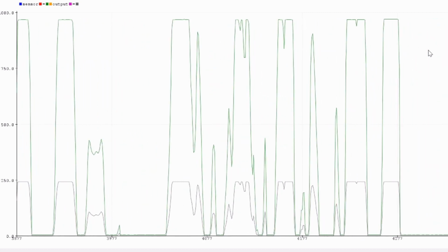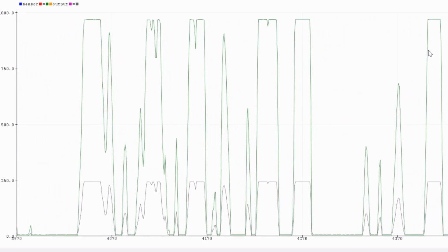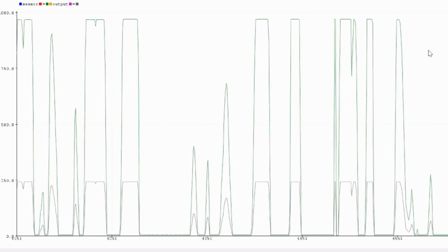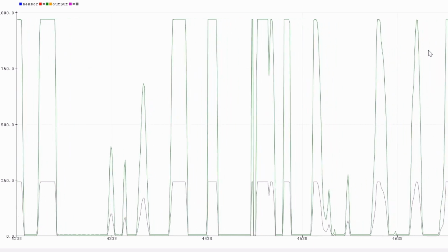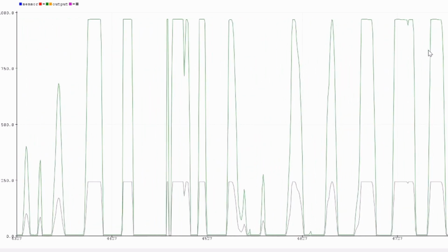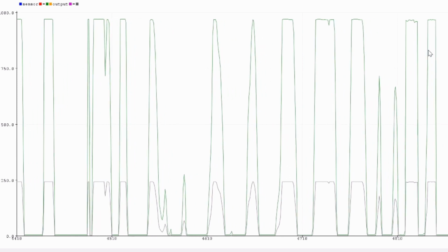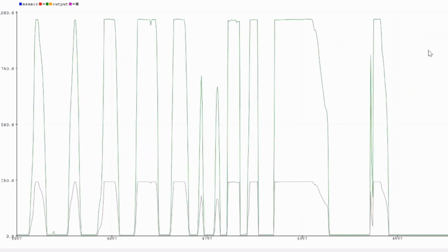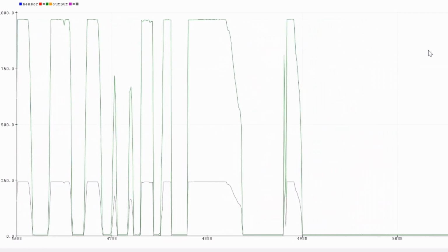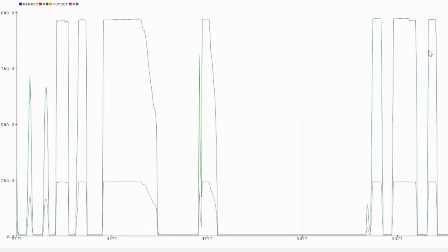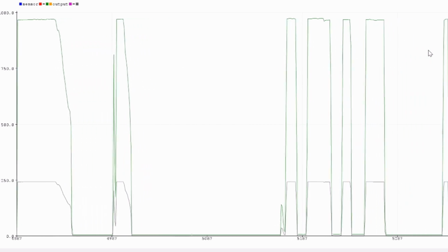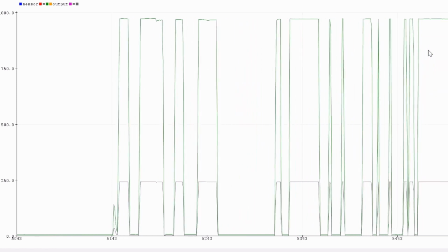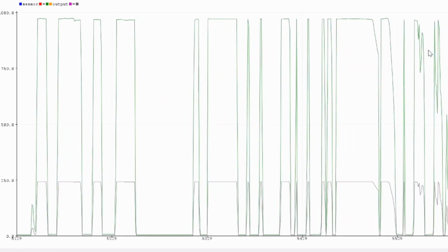If you've seen a cardiograph before, you realize it looks nothing like this. The main reason for that is something called clipping. The operational amplifiers only provide a maximum of 5 volts, and we amplified the signal more than the amplifiers could handle. This is a well-known case in audio. When somebody turns the gain way up and talks way too loudly, he'll probably get something that sounds like this. But since we're only looking for the number of beats and not how the beats look, this is okay.